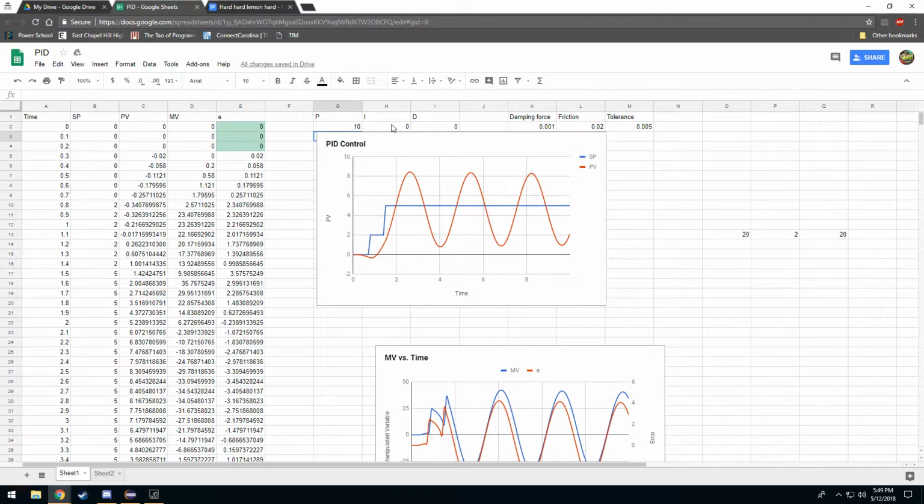So something you can do is the derivative term. That's the term you'd like to tune next, and the derivative term is dampening. If any of you have taken calculus or just know about it from hearing around, a derivative is your instantaneous rate of change. It's the rate of change of a function at any point along it. So if you know your derivative, you can apply a force based on your change in error. So not just your error. Proportional is just based off of whatever your error is. Your change in error can fix it.